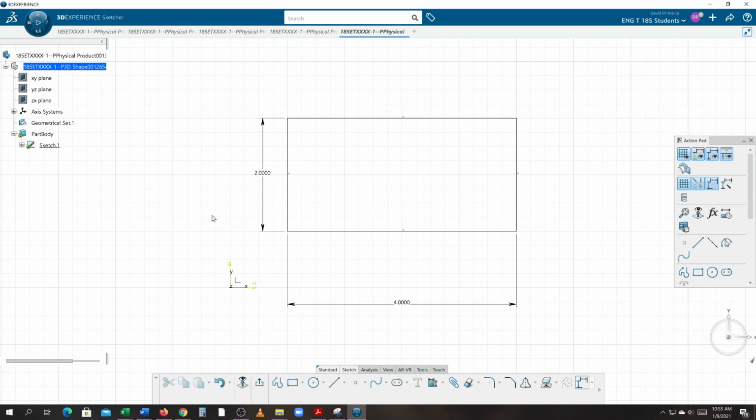Now, select your two lines at once by grabbing the Control button. Notice it shifts? No big deal. What I'm going to do here, actually it is a big deal. If that keeps shifting on you, one of the things you can do is hit undo, put it back to where it was. You can go to constraints and constrain here to here.